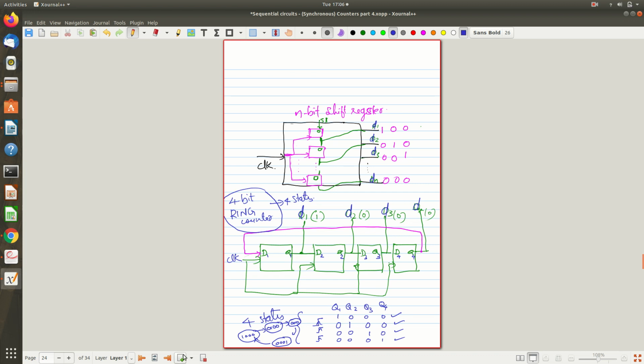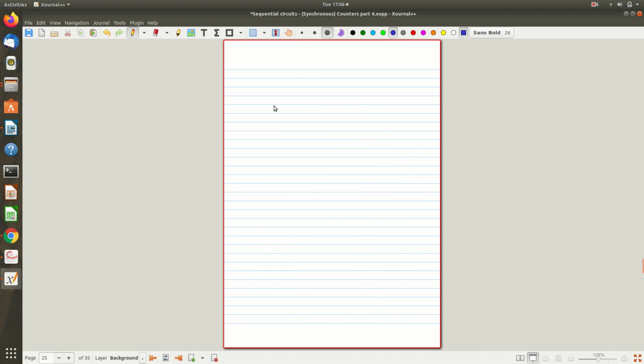So now let me give you a small analysis. The requirement is that I need n different timing signals generated. One thing I can do, if you remember what we discussed first, is use a counter. What kind of a counter? Not an n-bit counter. The counter is supposed to give an n-count sequence, so I can call it a mod n counter, okay? A mod n counter is nothing but a log n to the base 2 bit counter, okay? So both these things are the same.